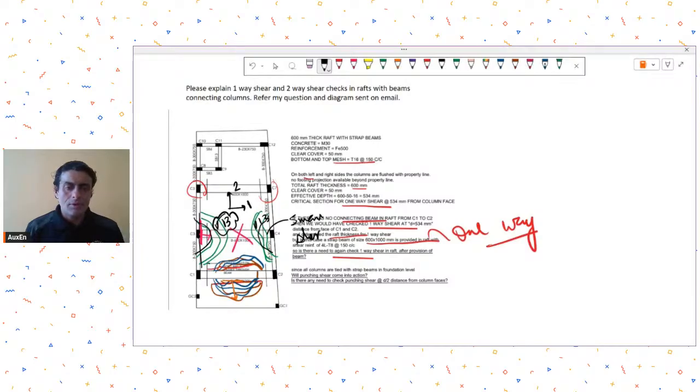So you have the option of, let's say, generally we see the forces and moments, but then you have the option of viewing the resultant stresses also, resultant shell stresses. So you check for S1 3 and S2 3, and then there is an option for S max. When you turn on this S max option, you get a good sense of how the maximum shear stresses are distributed. If you are getting a closed surface of this S max stresses, it is an indication that punching is critical or punching needs to be looked into.